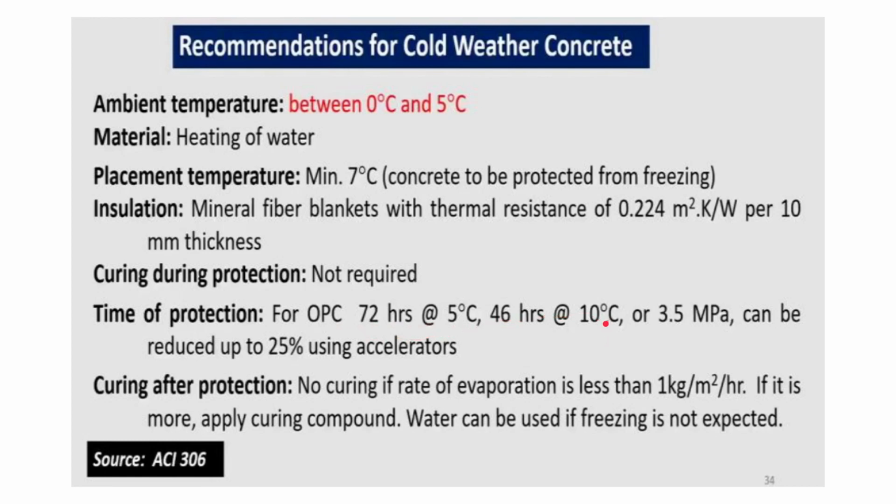If it is 10 degrees centigrade, it is lesser, 46 hours. And for 3.5 megapascal, whichever is reached first, like whichever is the minimum. So that is the time required for protection. And if we are using accelerator, it can be reduced up to 25%.